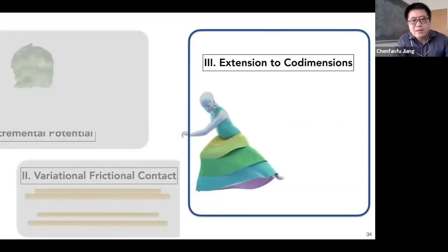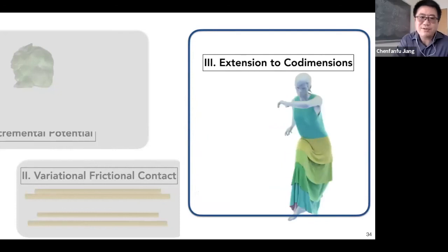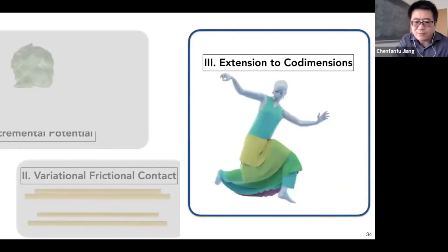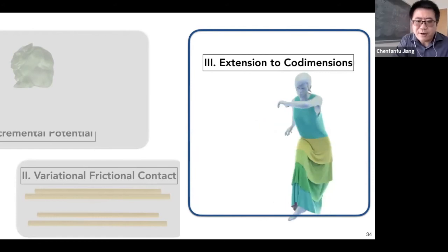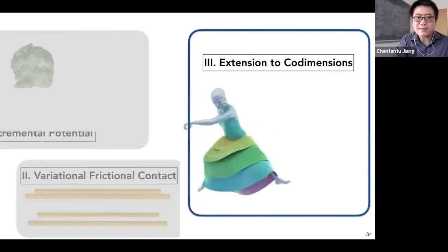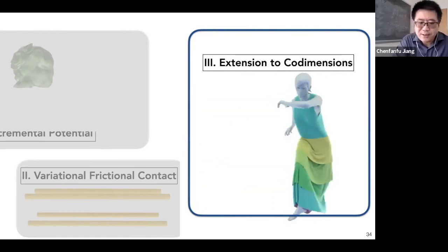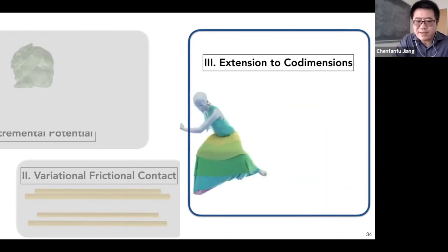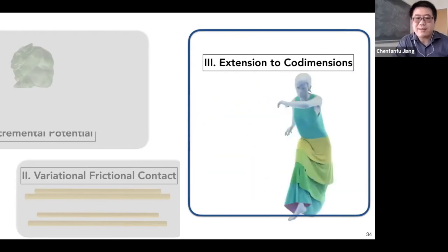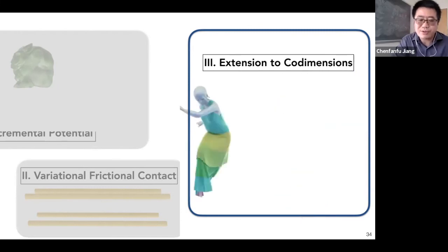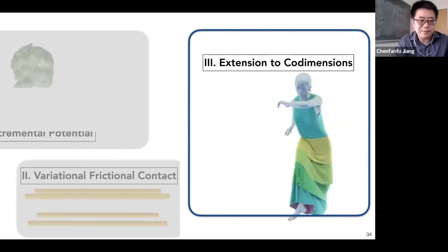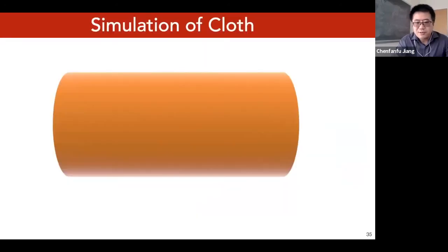Okay, so far all these simulations are done with volumetric bodies. Now for linear finite elements, every example so far you saw is discretized with tetrahedral mesh. And next, I'll briefly cover some extra ingredients, extending the contact model onto codimensional structures like shells and rods. So the frictional contact is barrier energies on the surface, so we can directly try it on shells.